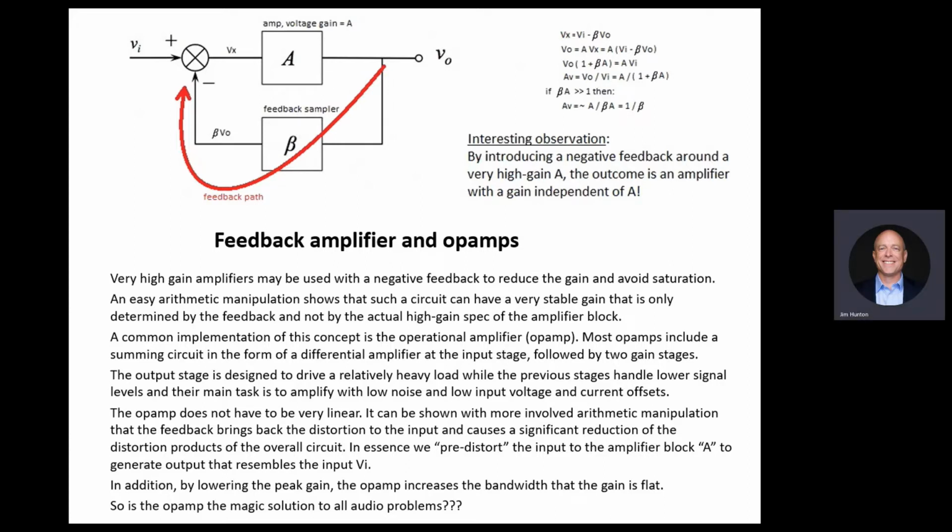You take a logarithm of that times 20, and that will be the level of negative feedback. So you can see that op amps start with a lot of gain and end up with a circuit with relatively low gain. So the negative feedback level is huge. We're reducing the original gain a lot.